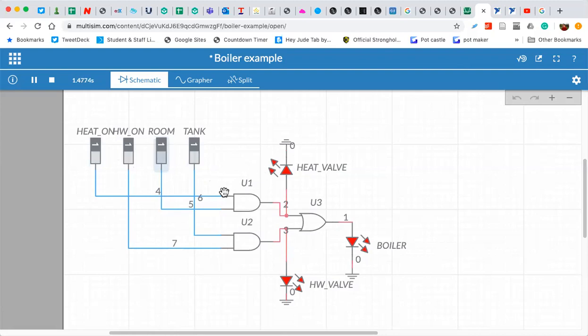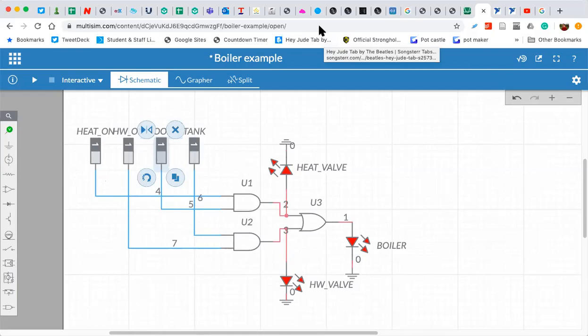So from what we had first go off, that quite complex circuit, lots of gates on it, we actually reduced that down using those Karnaugh maps to 3 gates, 2 AND gates and an OR gate. Okay, you are happy with that? Right, stop that.